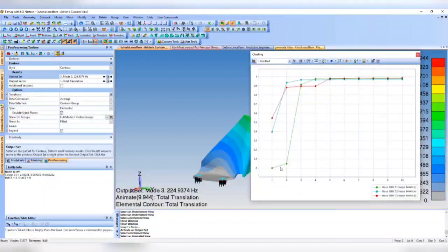Whereas for T1, most of it gets captured at normal mode 3. So you can see this big jump here. Most of that mass participation factor for that specific direction gets captured at eigenvalue 3. And what this is telling us is that the total summation converges around 4 to 5, basically around 4. It hits close to 1, which is your total mass effectivity.